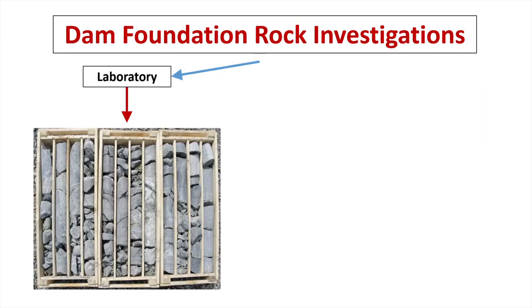Dam foundation investigations are mainly laboratory testing. This is done by carrying out drill holes at the dam location. Rock core samples are collected during the drilling, and they are stored and boxed with appropriate indication. Designers or geologists will recommend the particular samples for laboratory testing.